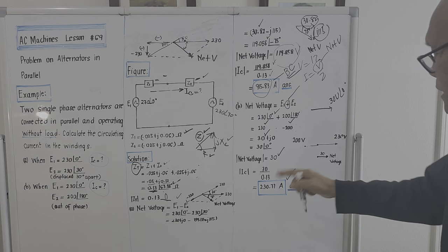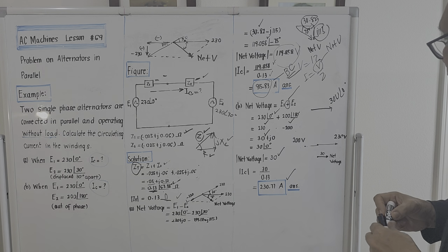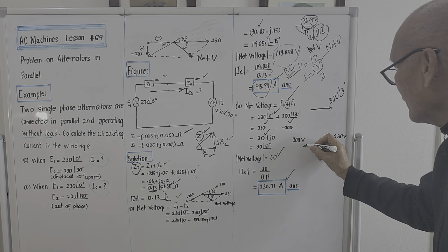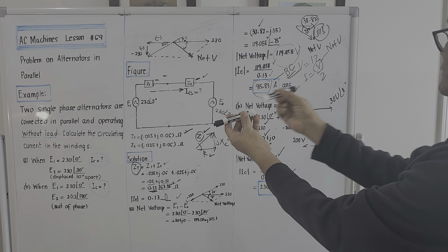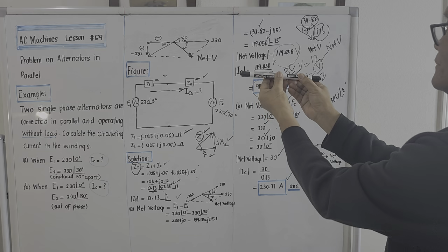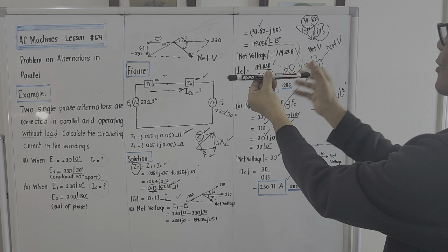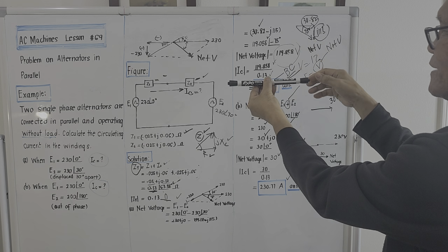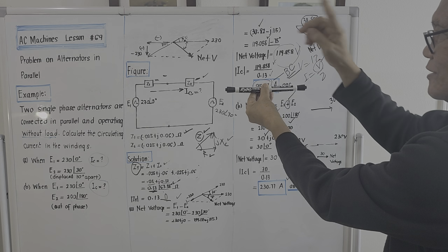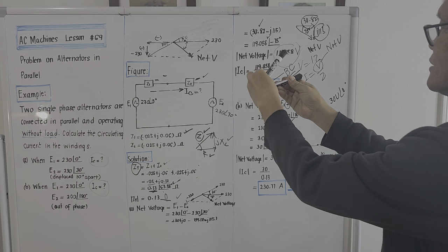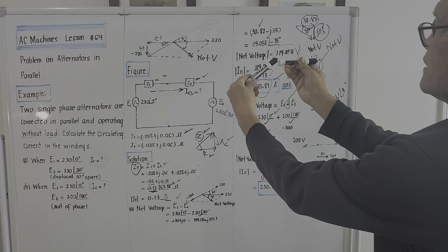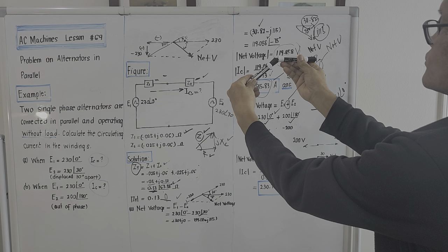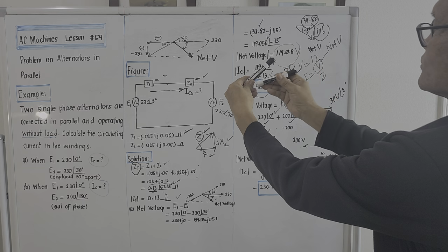Okay, why? How come this is smaller? Because the voltages for the second unknown are out of phase. The first voltage is to the right, the second voltage is to the left, right? So for the real part, it should be bigger minus smaller. That's the net voltage. In the first case, it is something like this. Then we take the negative equivalent, so the resulting vector sum will be by using the parallelogram.